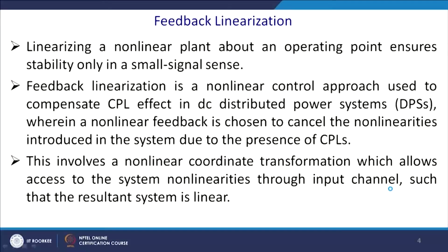So, linearizing a nonlinear plant about an operating point ensures the stability only in the neighborhood of the equilibrium. If there is a large change, the equilibrium point itself changes. So, all the studies which are applicable in small signal analysis are null and void.